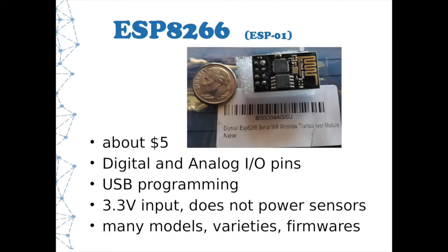So, who's heard of ESP8266? Okay, that's a lot fewer hands, and this is what I ended up landing on. They're cheap. This is the Rev 01 of this chip, this little one that I'm showing. It's got digital and analog inputs and outputs, USB programming. So it's similar to Arduino in capabilities, though it doesn't have as much flexibility as an Arduino does.